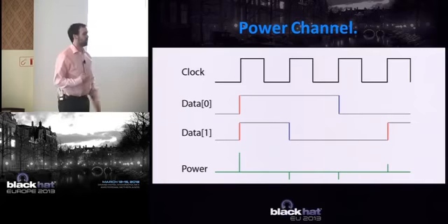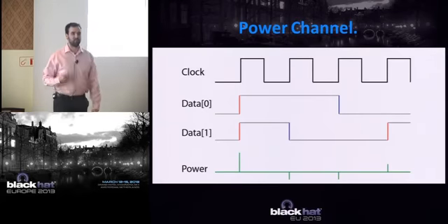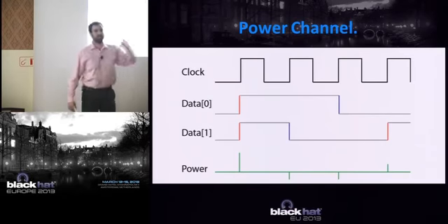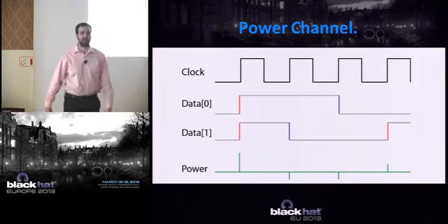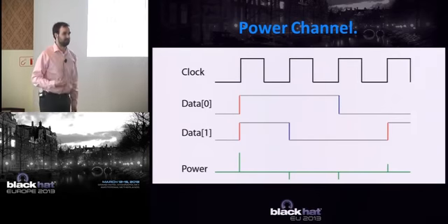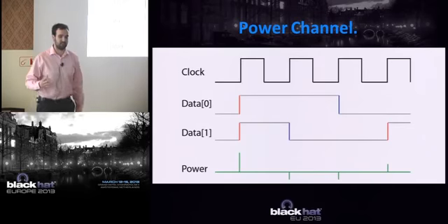Where this comes from is the buses do something called a pre-charge. You can imagine if the data bus switches from all ones to all zeros, this would be the worst case power consumption. This would require the most charge. Your worst case is going to limit your device in terms of speed and things like that, how fast they can go over the data bus.